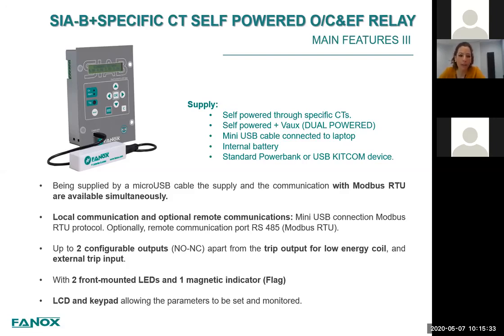The relay is provided with 2 configurable outputs, and the trip output is prepared to trip the low power coil or strikers. Also, we can check on the front 2 LEDs and 1 magnetic flag to signal that the trip has occurred.